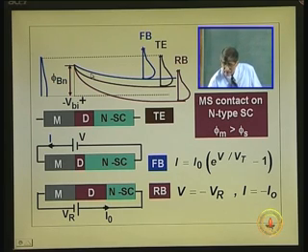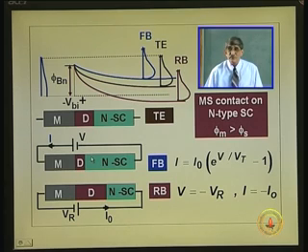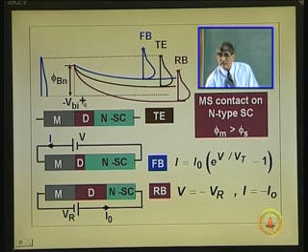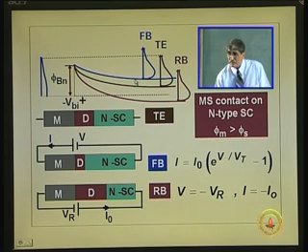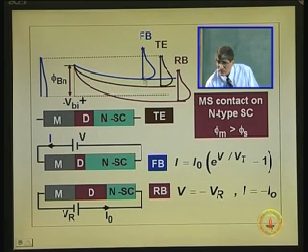Now, you can see the next diagram. In the forward bias condition, the polarity of this voltage is opposing the built-in potential. That means the total potential, what was here, is reduced, because that is lifted up now by an amount equal to the applied voltage. Now, the carriers also have the distribution with respect to that. The whole curve, what was brown, has become blue now.